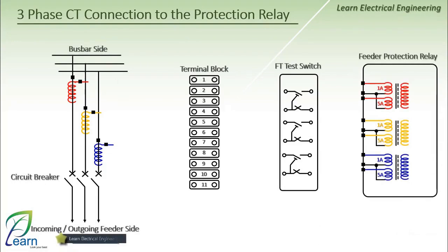Very good. Now we want to see together how we will connect these components with each other, meaning how we will connect our terminals, starting from the CT to the protection relay. The first thing we have is the three-phase current transformer, and the CT polarity we will use is subtractive. Each phase has 3 terminal blocks. Neutral has 2 terminal blocks.